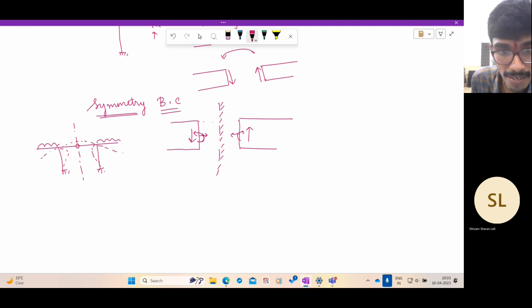If you see the bending moment, it is exactly what you see in a mirror. The axial force is exactly what you will see in a mirror. But the shear force is reversing its direction, which means the shear force on the left hand side is the same as the shear force on the right hand side. But since it is shifting the direction, only if it is zero can it obey the symmetry condition. That is the idea. So if it is non-zero, then it is not symmetric. The deformation is not symmetric.